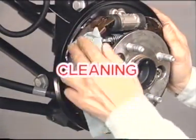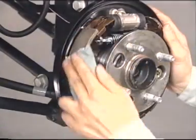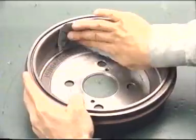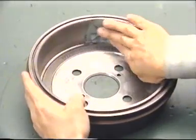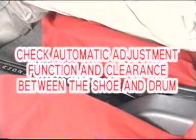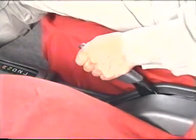After this, clean the brake lining. Be sure to wipe off any oil stains on the brake shoe lining using sandpaper. Also, clean the inside surface of the brake drum. Next, check the automatic adjustment function and the clearance between the shoe and drum. Confirm that the adjustment bolt rotates as the parking lever is being pulled.